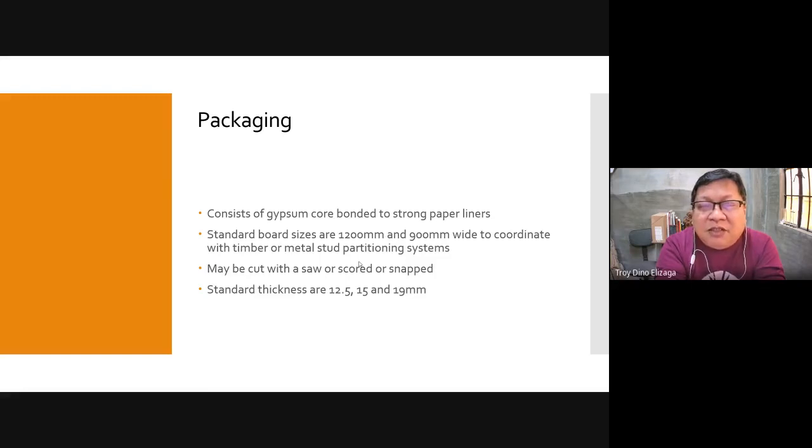But you cannot do this with gypsum board because it is 0.9. And 2 feet is like 0.6, so it has to be like 0.45 apart. So it's not square. You have to be very aware of the spacing when you make the construction drawings.